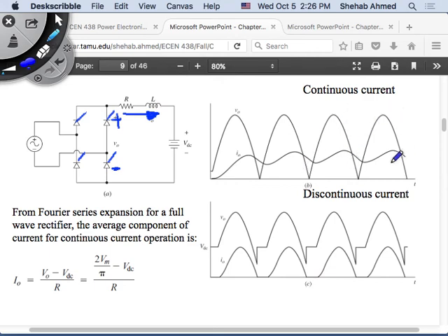When we add SCRs, we can make that value negative if I have an inductive load. And if you make it negative and keep the polarity of the current the same, then you flip the polarity of the voltage. Current is still going in here. Initially it looked like this, but now I would flip the polarity of the voltage. I will find a way to do this.